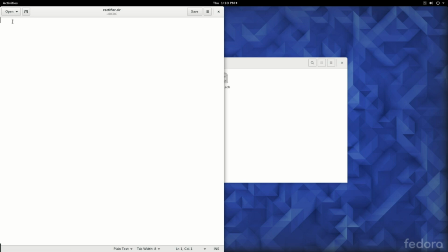And here, the first line is always a comment. So start from the second line. We would like to have a transient analysis performed, step time of 50 microsecond up to 100 millisecond using the initial conditions.